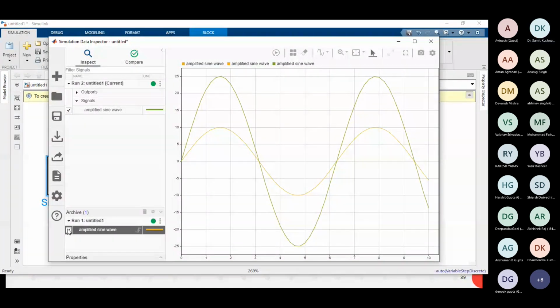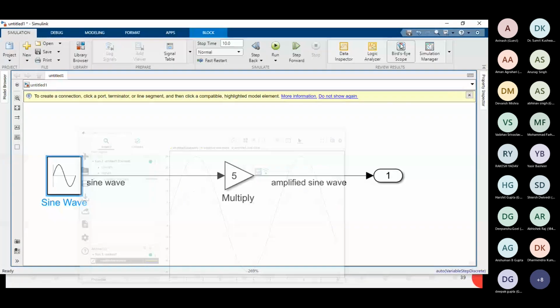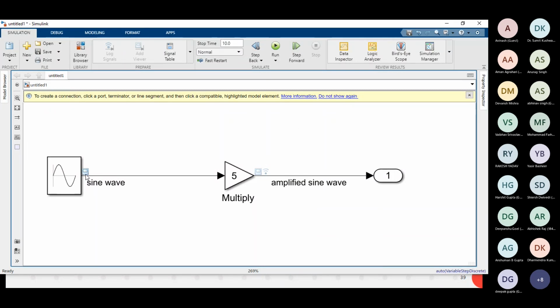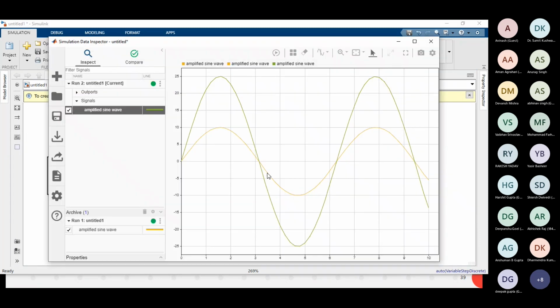Okay. So suppose you want to save, if we are going to change the value in any component, and for a specific value it will show one output, and now you want to display or save the result from the different parameter values. So we can insert this log signal, this log parameter. And using the data inspector from here, now I am just changing the value. Now let me open the data inspector. So now I can see both values here.